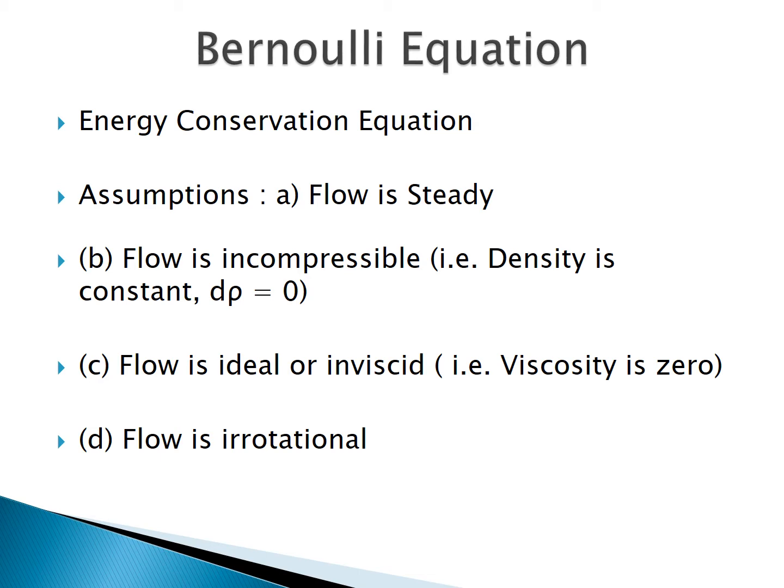change in its density. Then the third assumption would be the flow is ideal or inviscid, that is, the viscosity is 0. Ideally, viscosity is not 0, but we are considering it as 0 because viscosity in fluids signifies losses. Here we are considering that there are no losses, which is not practically possible, since losses exist. So it is another assumption that the flow is ideal or inviscid. That means there is no viscous forces in the fluid.